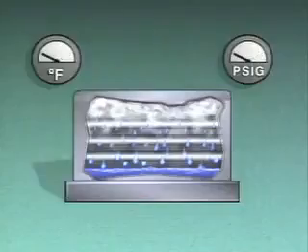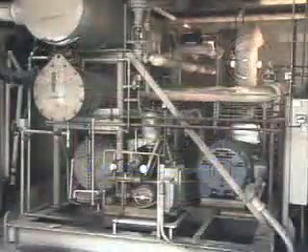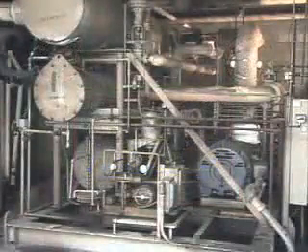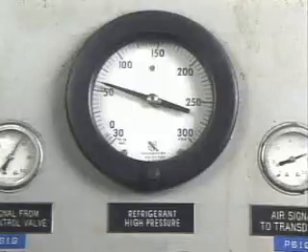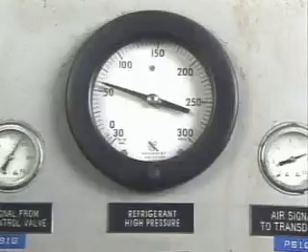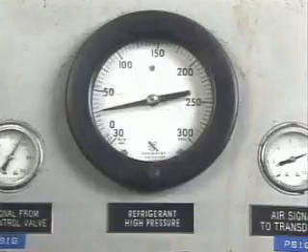The same effect occurs with the refrigerants in refrigeration systems. When the refrigerant is at a higher pressure, it boils or condenses at a higher temperature. When the pressure of the refrigerant is reduced, it will boil or condense at a lower temperature.